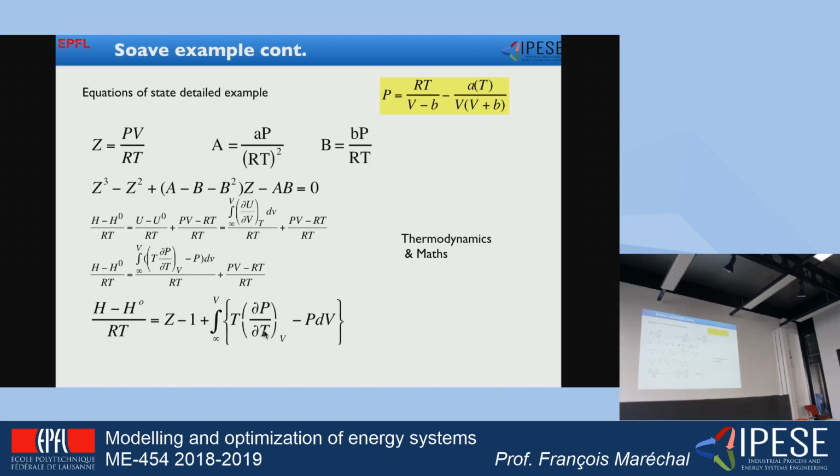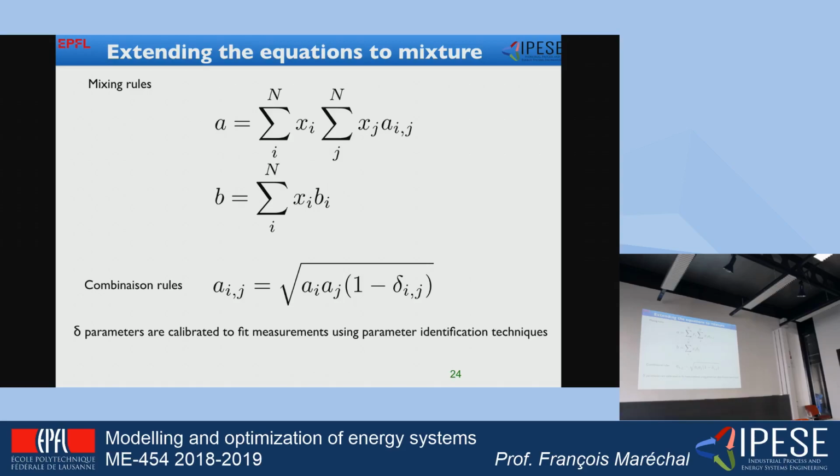The other dimension that is really interesting is that the values of A and B can be related to the composition. So there are rules that give us the values of A and B when the composition changes. If I have more ethanol in water or less ethanol in water, so ethanol in water is beer, I will have another behavior with respect to the evaporation.